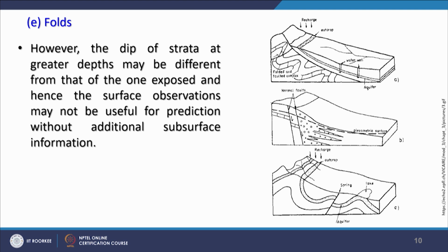So, faults play a very important role, and while doing this kind of investigation from a groundwater exploration point of view, this knowledge is very important about that particular location. If somebody is working in a granitic terrain, then you may not encounter such structures. But if somebody is working in a sedimentary or metamorphic terrain, then one should be completely aware. This knowledge can be collected through measurements of basic data, that is the attitude of bed, dip, strike and plunge, and other things related with borehole logging, and a lot of prediction about subsurface geologic condition can be made from this superficial data.